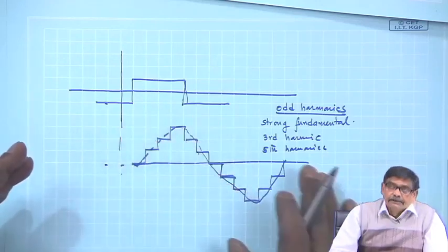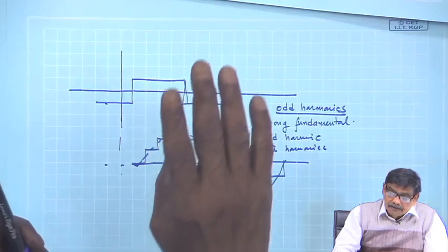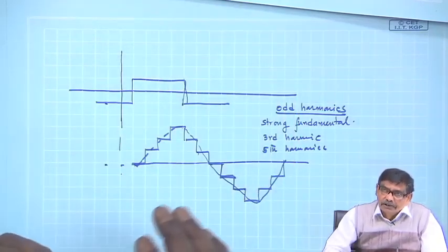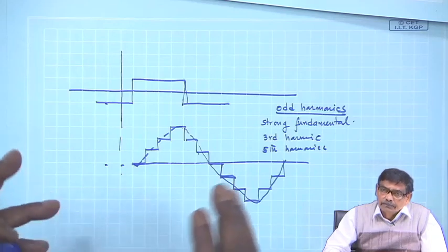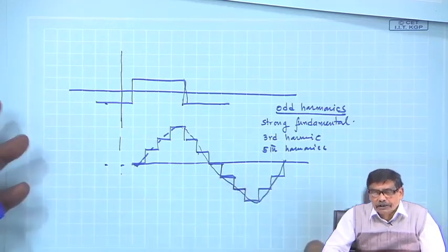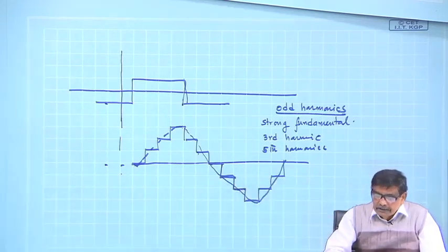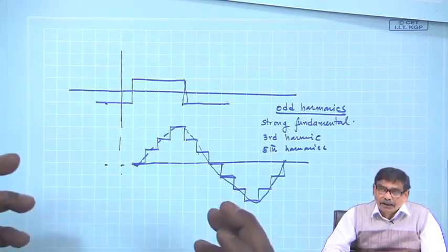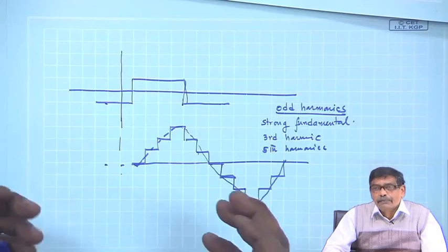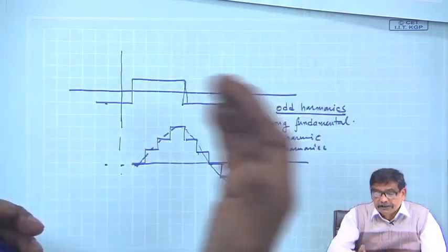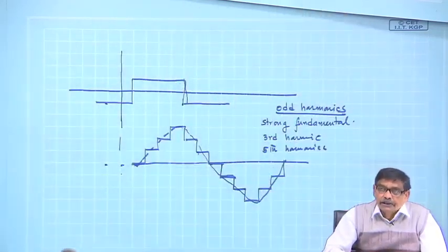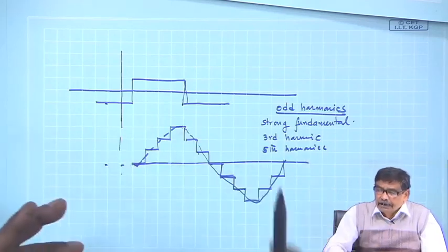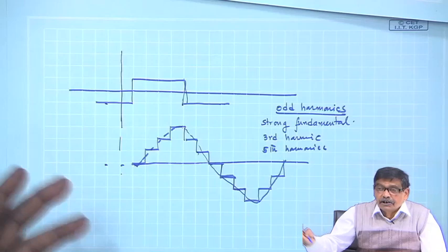in such a scenario, you have to construct a machine to have sinusoidal B distribution. Why sinusoidal B distribution? Because you want to generate sinusoidal voltage. Therefore, using a single coil to have a space variation, theta variation of B sinusoidal, no, that is not possible. That is pure rectangular square wave like inverter output voltage.